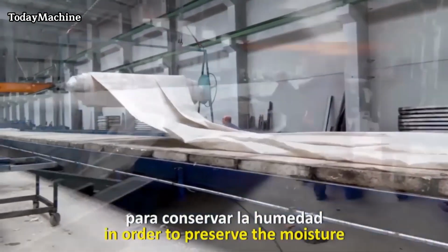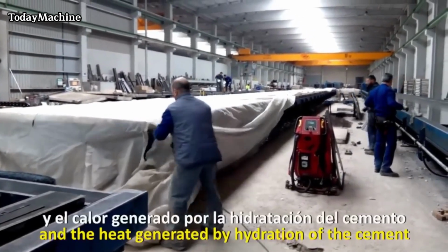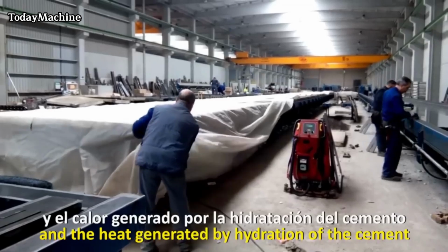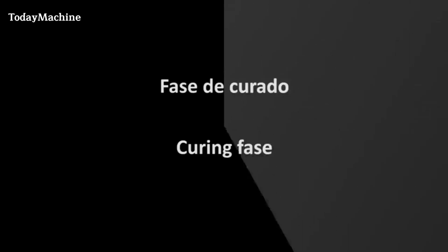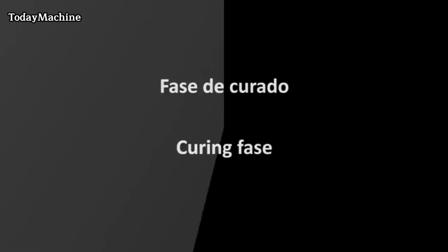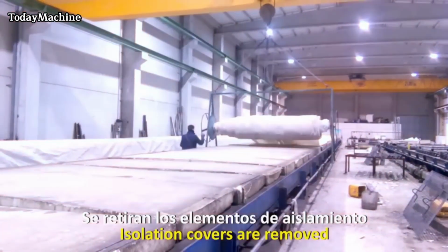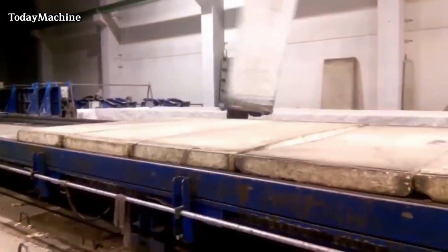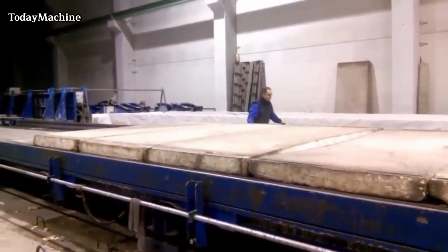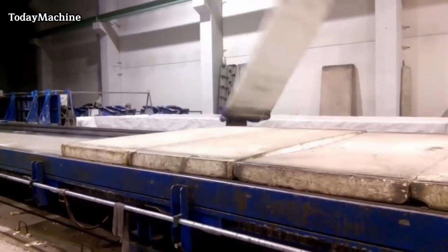After vibration and screeding, it is advisable to cover the concrete with a protective material. This protective covering serves multiple purposes. Firstly, it helps in retaining moisture within the concrete, which is essential for proper curing and achieving the desired strength. Secondly, it protects the concrete from external factors such as temperature fluctuations and debris that could affect the quality of the panels. Properly covering the concrete ensures that it cures uniformly and reaches its full strength potential.